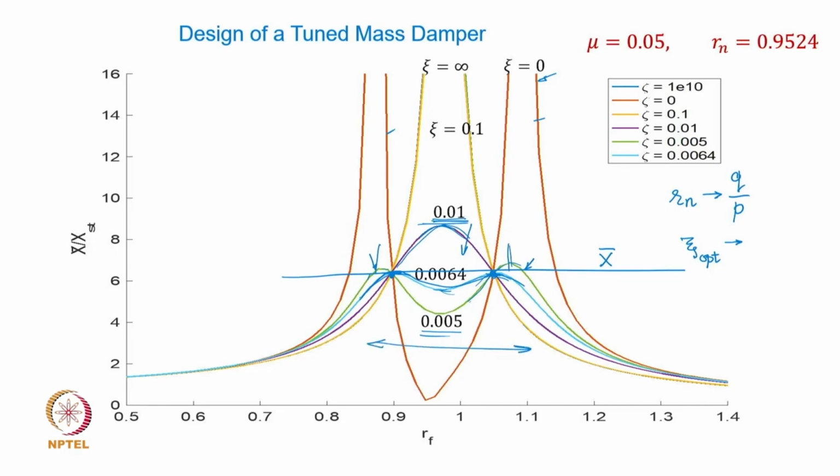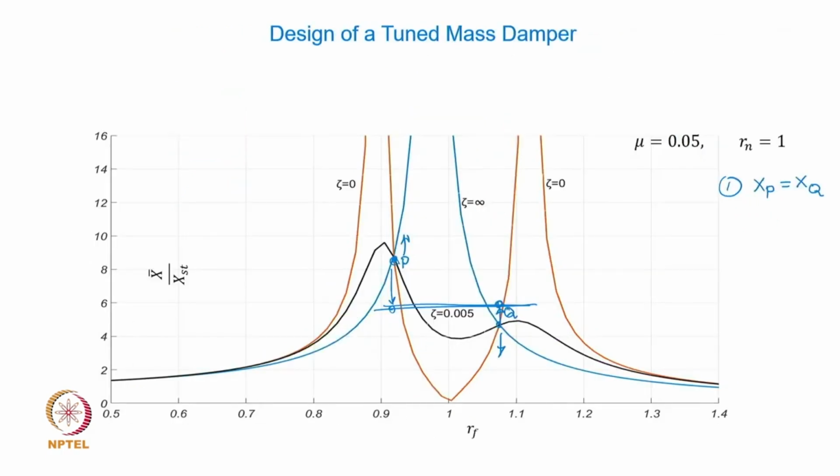Okay, and then the fact that for an undamped vibration absorber, the problem always is large amplitudes at the nearby resonances and limiting a very strict regime of operating condition. That gets relaxed, and then you don't have to worry about resonances throughout the operating speed range. So this is the basic philosophy of the tuned mass damper design.